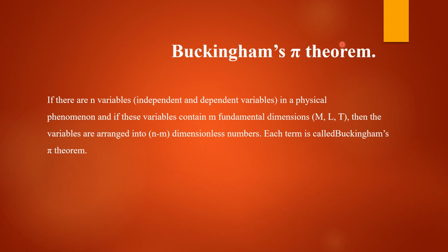What about Buckingham's pi theorem? If there are n variables, independent and dependent, in a physical phenomenon, and if these variables contain m fundamental dimensions, that is M, L, T, then the variables are arranged into n minus m dimensionless numbers. Each term is called a Buckingham pi term.